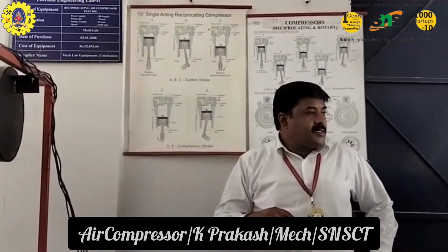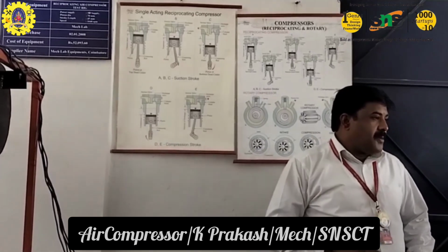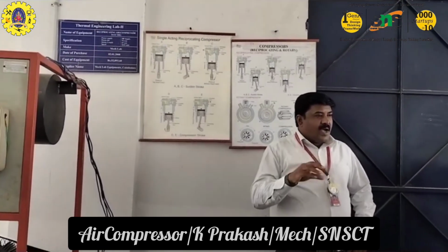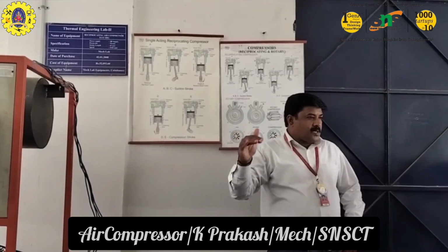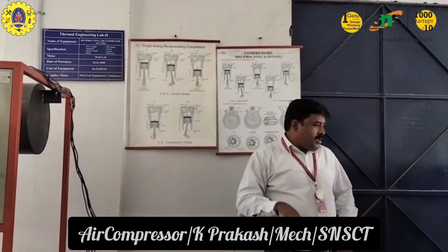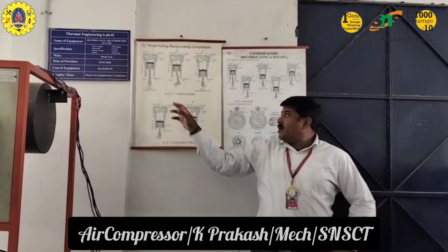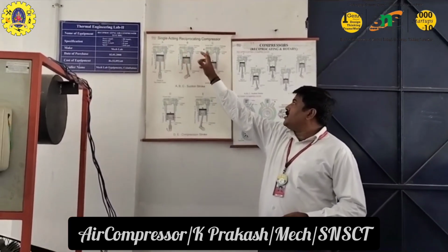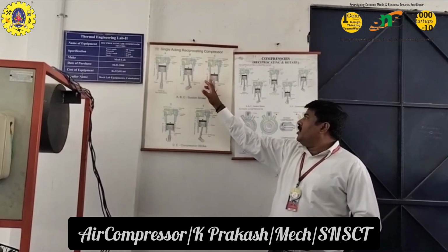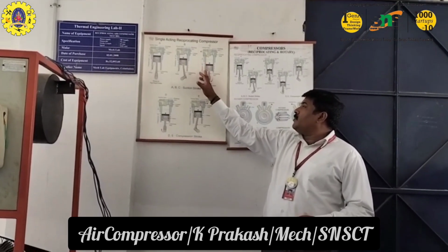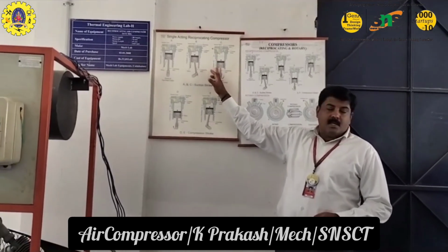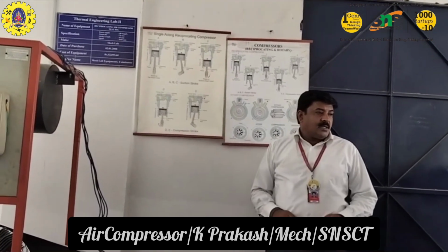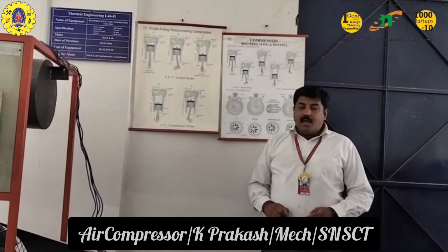has lesser pressure when compared to the atmospheric pressure. So the air tends to move from the high pressure area to the low pressure area, so automatically air comes inside. The piston is coming downwards from TDC to BDC, so this amount of air is coming inside. So this is suction.